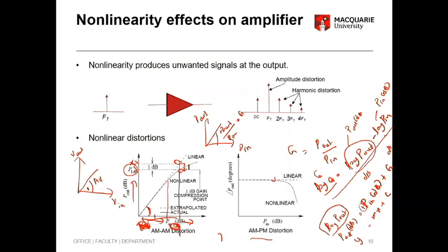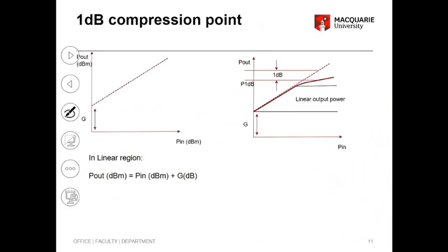You guys haven't really dealt with that because it wasn't very important for LNA. That means with the input power, you can also look at the phase of the output. Things like phase shifters will actually look at phase. They don't really worry about the amplitude of the output, right? So for them, when you work at different power ranges, you'll need to make sure your phase doesn't change. See, this phase is constant, irrespective of your power input level. But if it starts dropping at a certain power level, the phase shifter is not useful anymore. So depending on other applications, you can have phase distortion as well. I've sort of discussed this when we were talking.